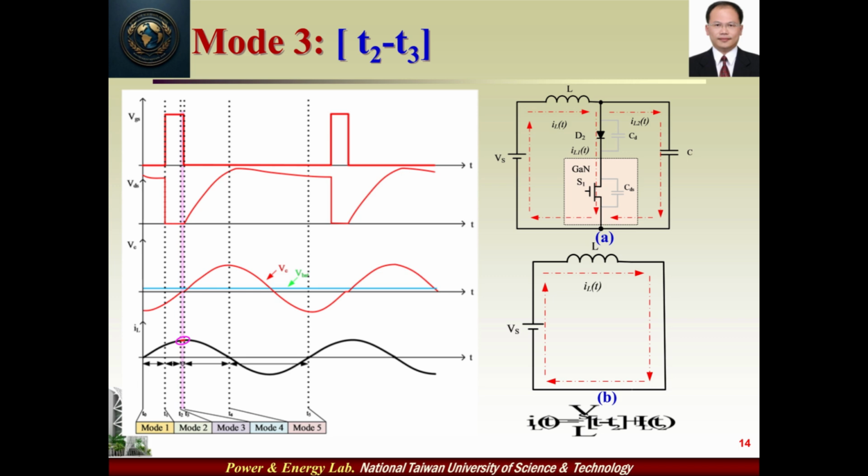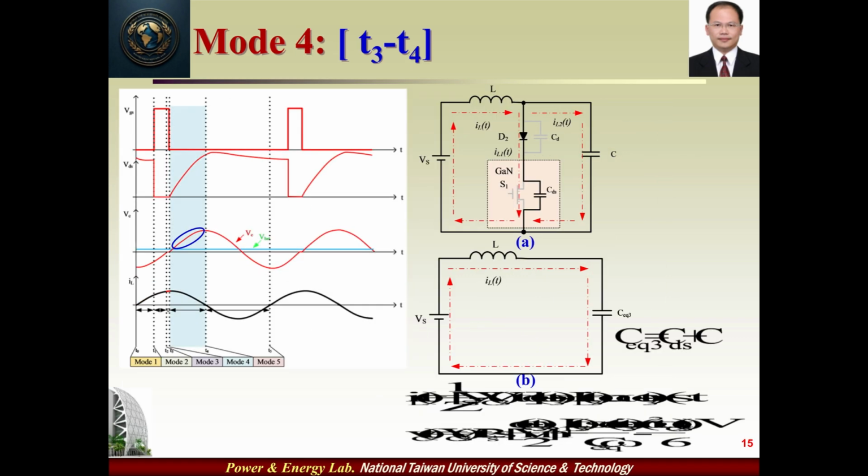In this mode, the sinusoidal load is continuously drawing energy from the battery module during the positive semi-cycle. When the switch S1 is turned off, this mode is ended. In this mode, the switch S1 is turned off, and the inductor current IL(t) decreases to 0.